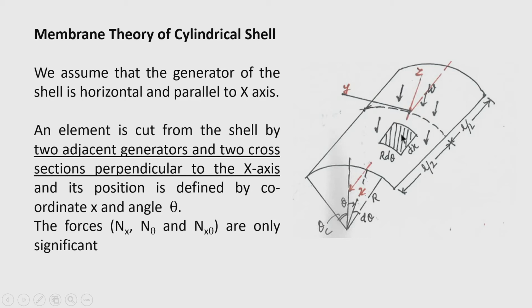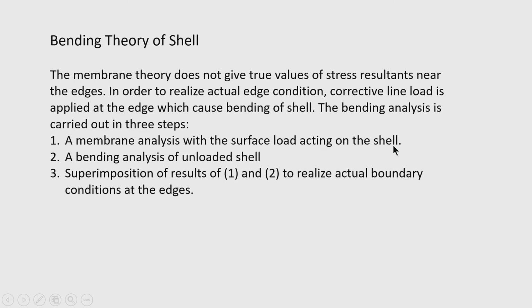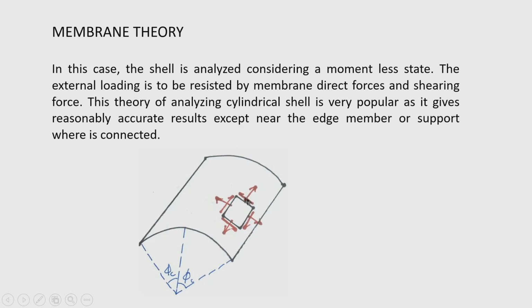N x is the membrane force along the longitudinal direction, N theta is the force in the circumferential direction, and N x theta is the membrane shearing force that I have shown in my earlier slide. These are the membrane shearing forces. And this is N x directed towards the x axis and this is N theta.